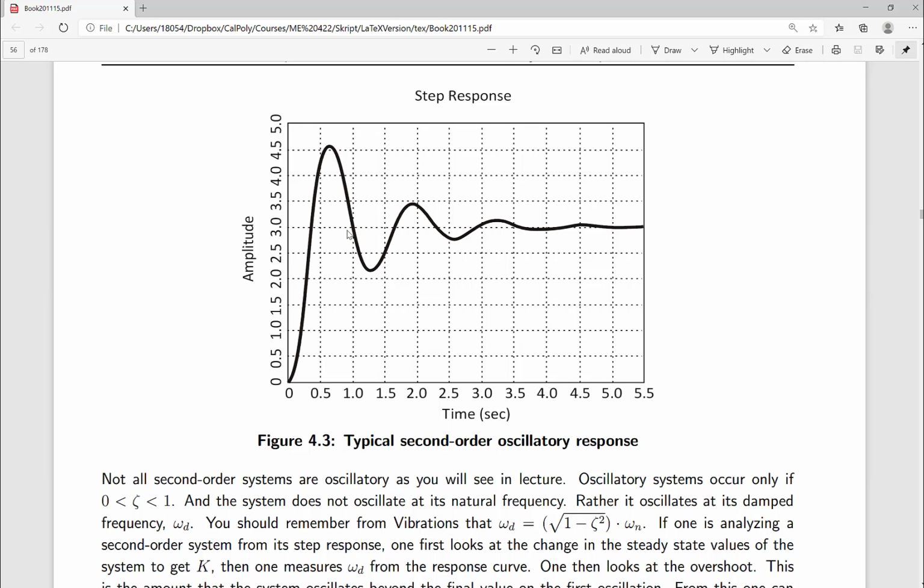When you're moving something, especially in a confined space, which you often find in manufacturing environments, right past point B there could be some obstacle that you're going to hit if you go too far. So you're limited in your overshoot so that you don't have mechanical interference between something you're moving and some part of the space that's not moving.